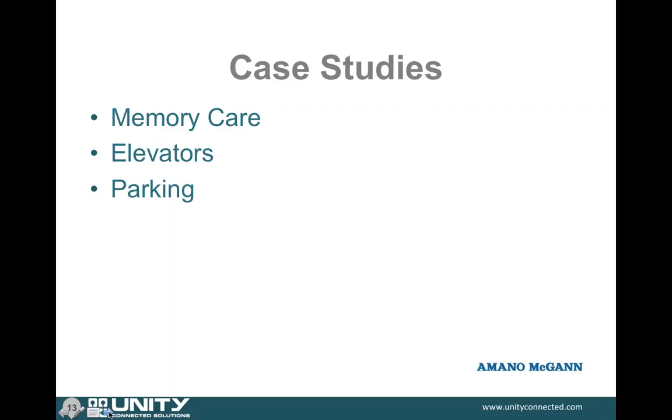So memory care is generally a lockdown area. You don't want the residents to be able to leave, and you don't want just anybody coming in. So you have it locked down. We lock it down with magnetic locks at all the doors, whether it's a stairwell door or a main door going into it. And then we put readers on both sides of the door. So if anybody wants to leave that area, they have to have the credentials to leave and or go in.